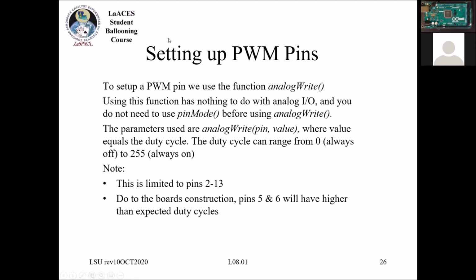We're not really going to use this too much in the activities, but it could be something that's useful for your payloads. So you would probably like to know how to use pulse width modulation. It's the same sort of thing, except you have an analog write. Obviously, you can only use it on those designated pins, but it's a similar sort of thing where when you call the write, you tell it what pin and what value I want.